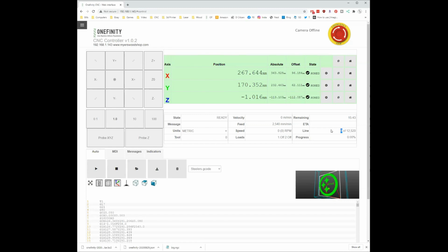You can kind of hear it. Once you cut enough, you can hear like, that sounds like it's struggling. My first thought would be to go in and turn the router up a little faster, by 0.5, or I don't know what it is. If I'm going from 3 to 4, I'd go to like 3.5, and then you can kind of hear if it's working correctly, because you should have that nice clean sound, not a struggling kind of sound, you know what I mean? Yep.